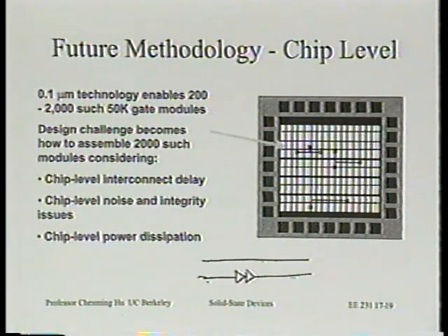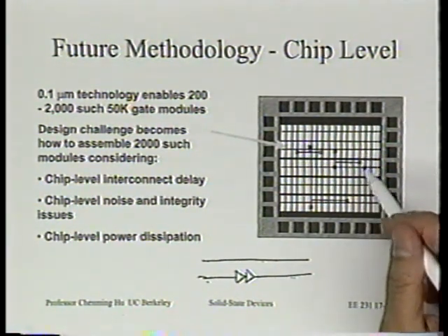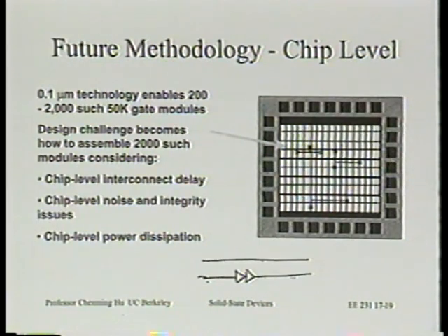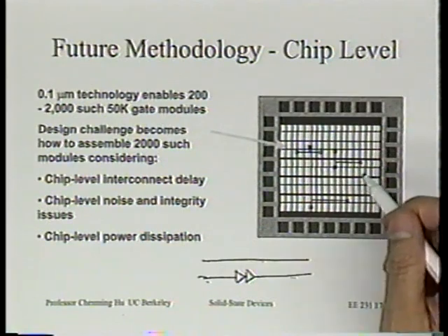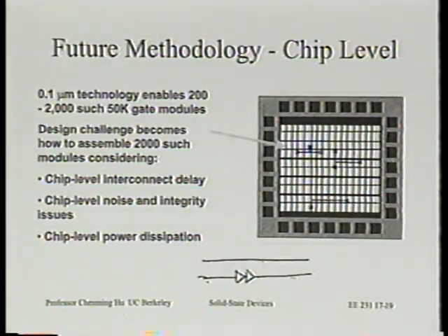And so other ideas would be for these type of interconnect between the blocks, we would dedicate a layer of metal which we use fairly thick metal to minimize the resistance, and we also use fairly low density metal lines, so the distance gap between the metals is large, so we don't have much capacitance. You see what we're talking about? Because the density now is much less now. You're only trying to connect a few hundred of blocks rather than millions or billions of transistors.